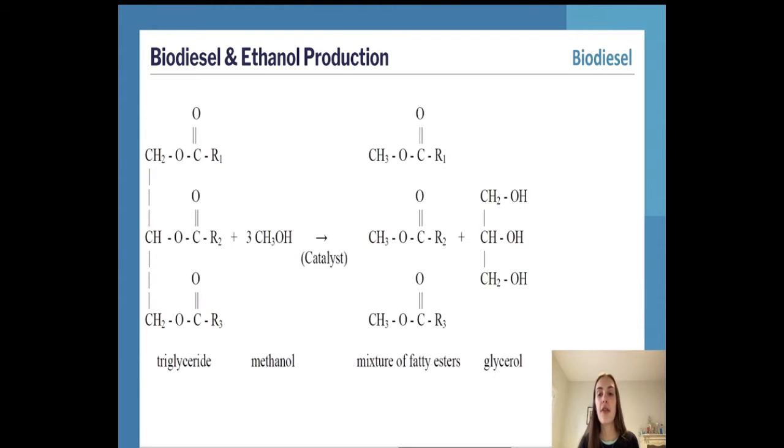A sample of the clean feedstock is also tested via titration against a standardized base solution to determine the concentration of free fatty acids present in the vegetable oil. These acids are then removed typically through a neutralization reaction or are esterified in order to produce biodiesel or glycerides. We can see the reactions we use as shown on the screen here.